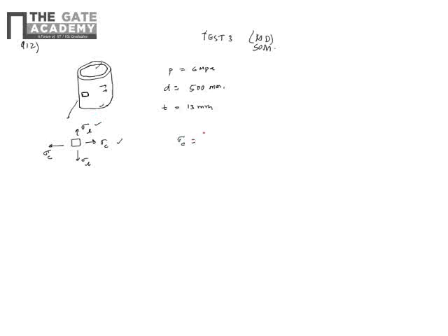Now the circumferential stresses, when we get by the force balance, we get it PD by 2T. PD by 2T is the circumferential stresses, whereas the longitudinal stresses is pressure diameter by 4T. Now this you will get from just taking a section at the circumference, and then the force balance, the external force being due to the pressure, and the internal force from one part to the other part. Okay, so all that basically taking a section in the circumferential and in the longitudinal direction, you get expressions for circumferential and longitudinal stresses.